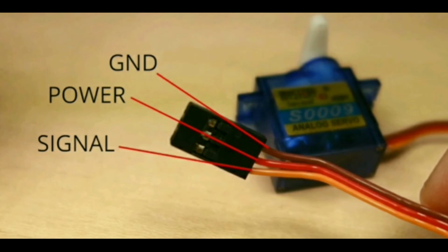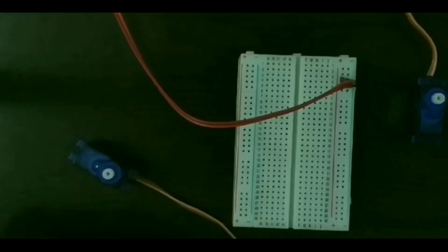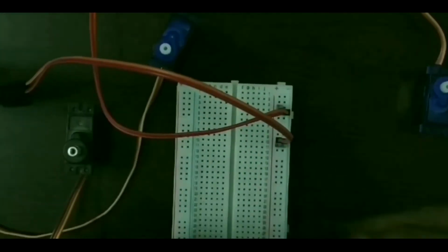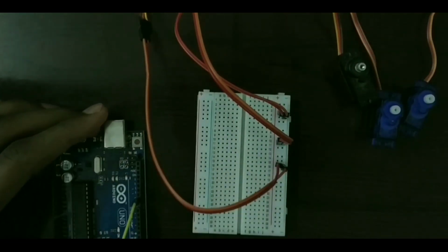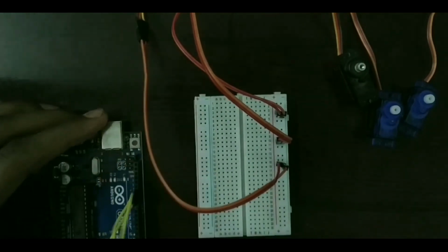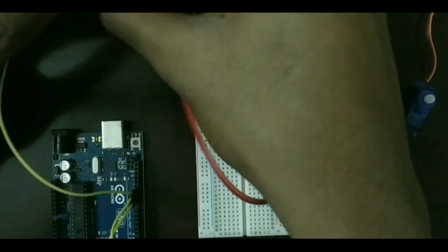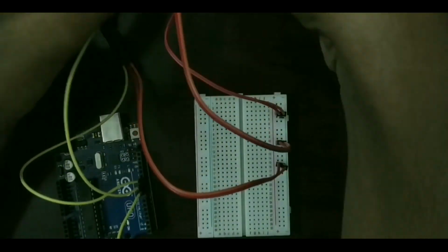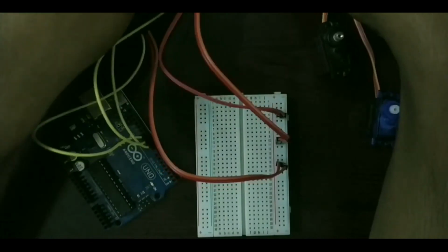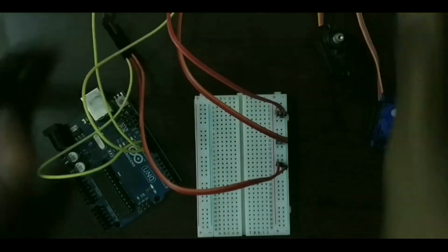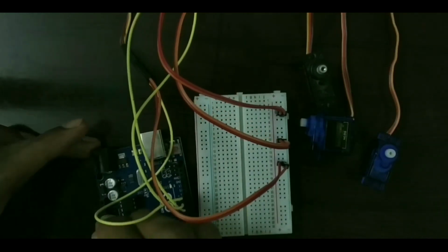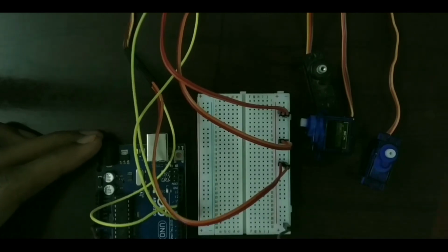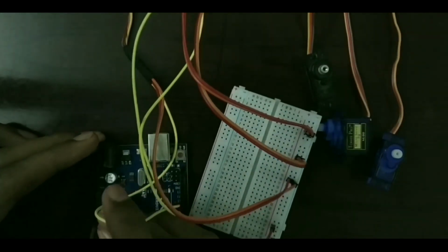Connect the VCC and ground pins on the servo motor to the breadboard's power rails. Now connect the signal pins on the servo motors to pins 9, 10 and 11 on the Arduino Uno. The order of the arrangement does not matter, since we will be giving the same command to all the motors. Using the jumper cables, connect the ground on the Arduino to the ground rail on the breadboard and 5V to the power supply rail.